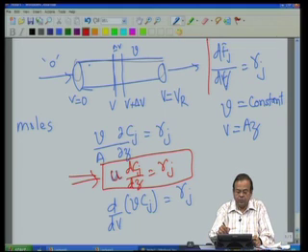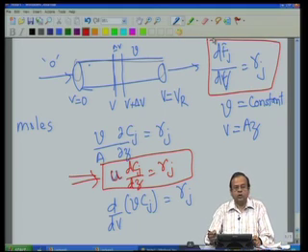The general mass balance equation is this particular form, dFj/dV equal to Rj, which under the conditions that volumetric flow rate is constant through the entire reactor, that means there is no change in number of moles for a gaseous reaction, or if it is a liquid phase reaction, that is a reasonable assumption.